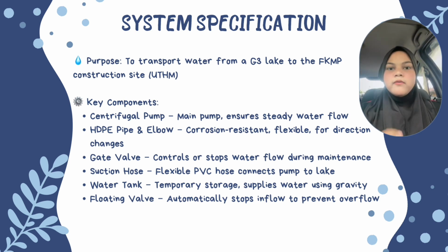To prevent overflow, a floating valve is installed in the tank. The valve automatically stops the water inflow when the tank is full, ensuring safe and efficient water management without the need for manual intervention. Overall, this system is designed to be practical, efficient and reliable for continuous operation on site.